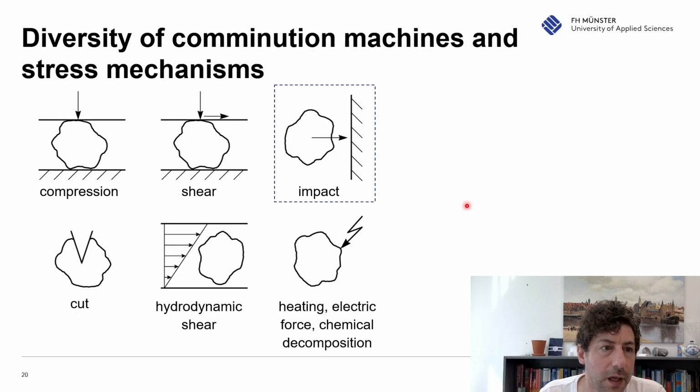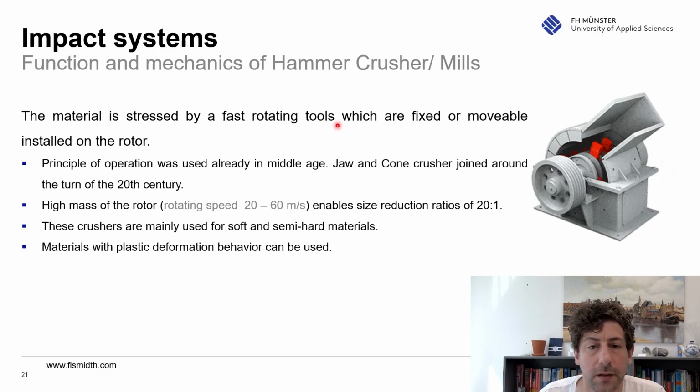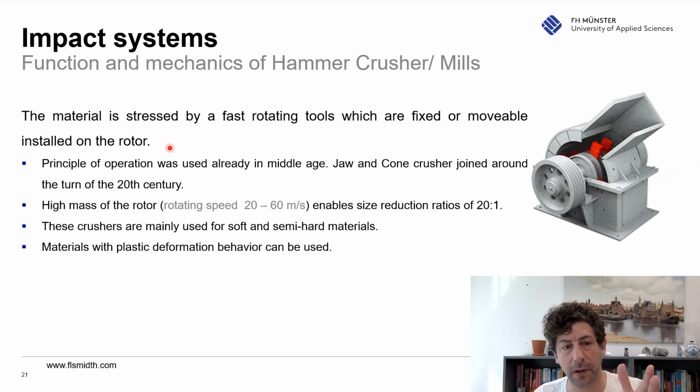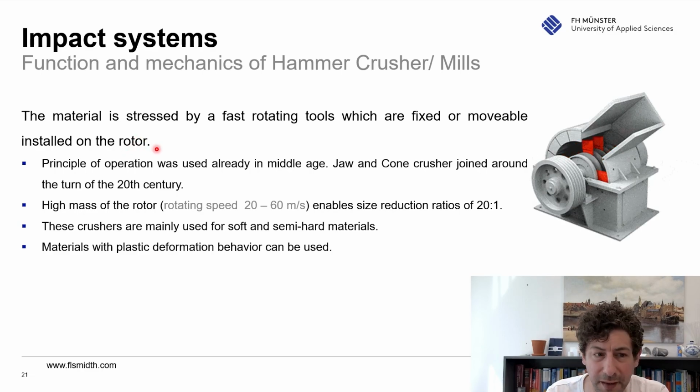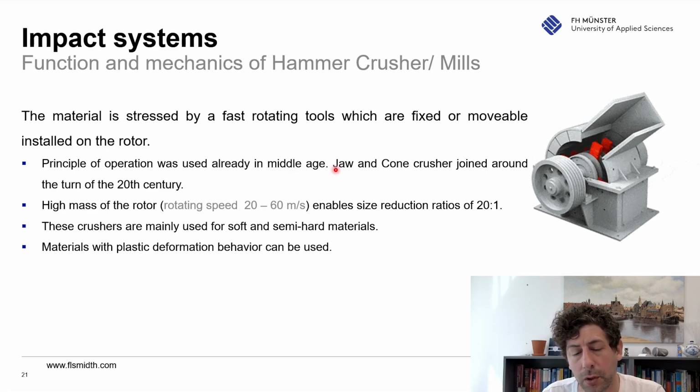next step. Okay, a last one I would like to show you is an impact device, and the impact device could be a hammer crusher or a mill. So the material is stressed by very fast rotating tools, which are fixed or movable, installed on the rotor. So here you hit the particles, and this is a very old method. The principle of operation was used already in the Middle Ages. Jaw and cone crushers and so on were joined around the beginning of the 20th century, and are now, of course,